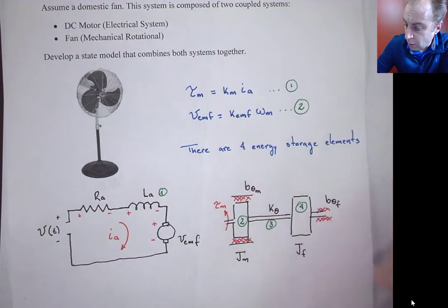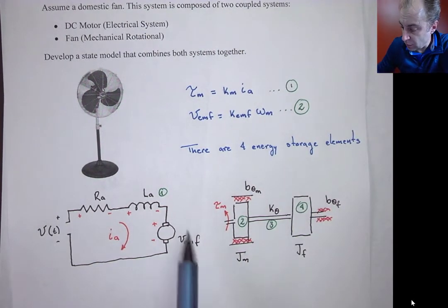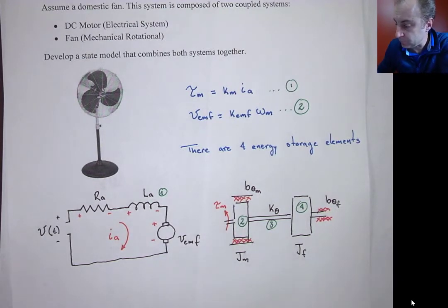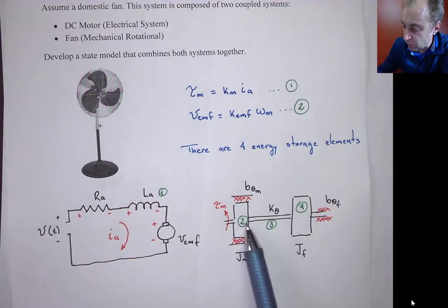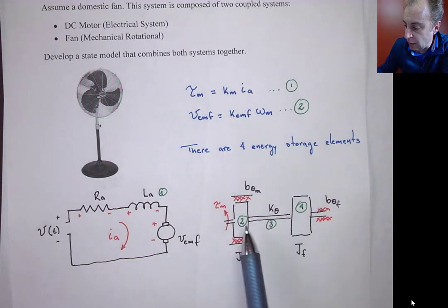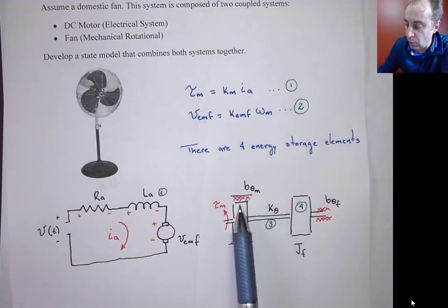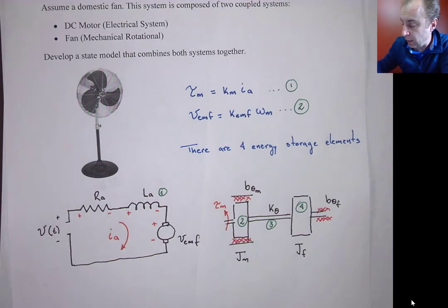Now all of them are independent. There is no dependency among them. And as I mentioned before, if that was a rigid link, then we would have the whole system here would be just a single inertia element. So at the end, it would be a 2-order system instead.